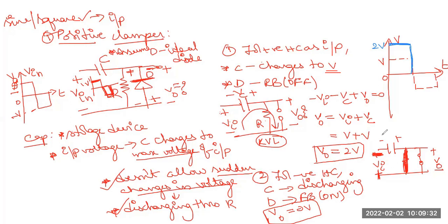Now what do you guess is this capacitor voltage here? So you apply KVL like this. The capacitor voltage is Vi minus VC plus V naught, but V naught is 0, right? So finally you are left with the capacitor voltage equal to the input voltage Vi. This is only for information, we are evaluating, that's all. Nowhere in the output waveform are we going to show it. The output waveform we categorize only for these two.